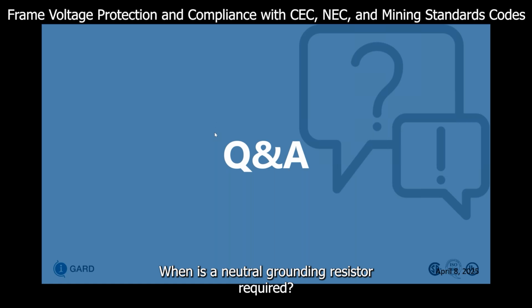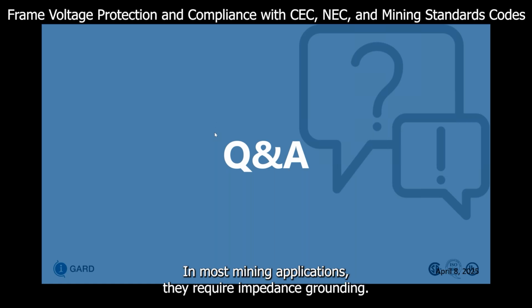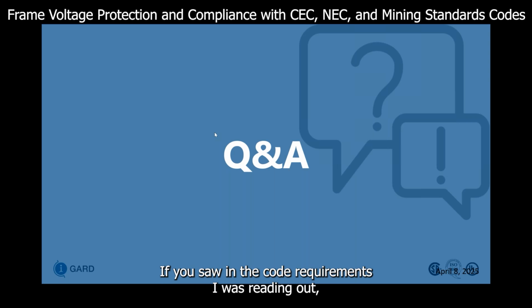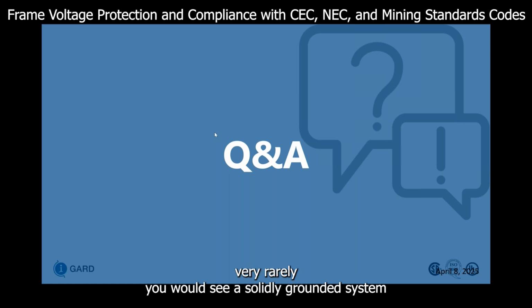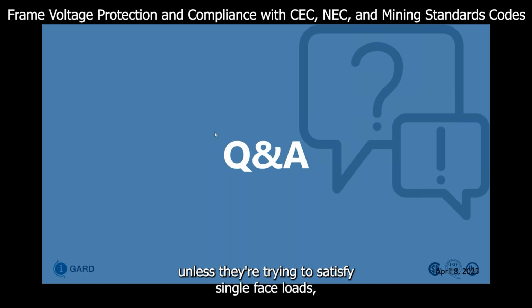When is a neutral grounding resistor required? In most mining applications, they require impedance grounding. If you saw in the code requirements I was reading out, they say that the system shall be resistance grounded. If you have a delta system, a neutral should be established. Even in CSA M421, it's pointing more towards resistance grounding, and very rarely would you see a solidly grounded system unless they're trying to satisfy single phase loads. For oil and gas as well, they also exclusively use resistance grounding.